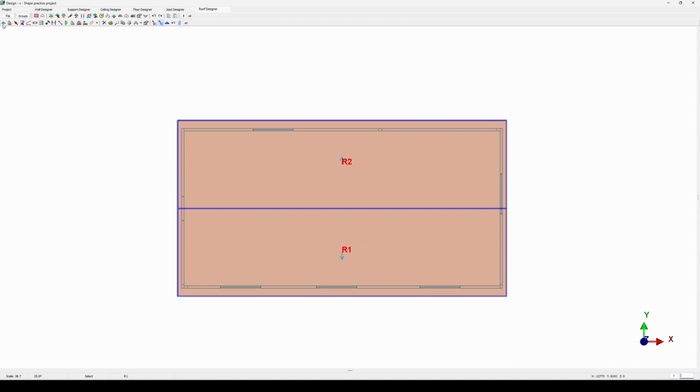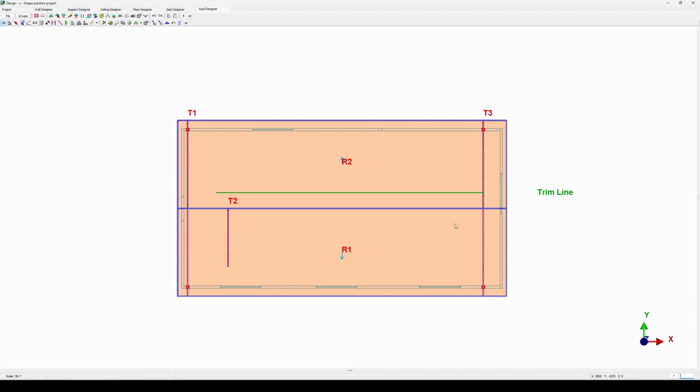The next step, we'll go to the Draw Truss tool, the very first one. Select that by using the left click button. Now to draw your trusses within this project, we are going to start from the outside of my project and finish it off on the opposite end. And remember, on the outside of that project. The reason we do this from outside to outside is if you start on the inside, for example's sake, we'll just draw it right there, it has some difficulty snapping to the full shape of your roof. So we'll make sure that we go from outside to outside, not the inside. Otherwise, it will only snap half of the truss onto this project.